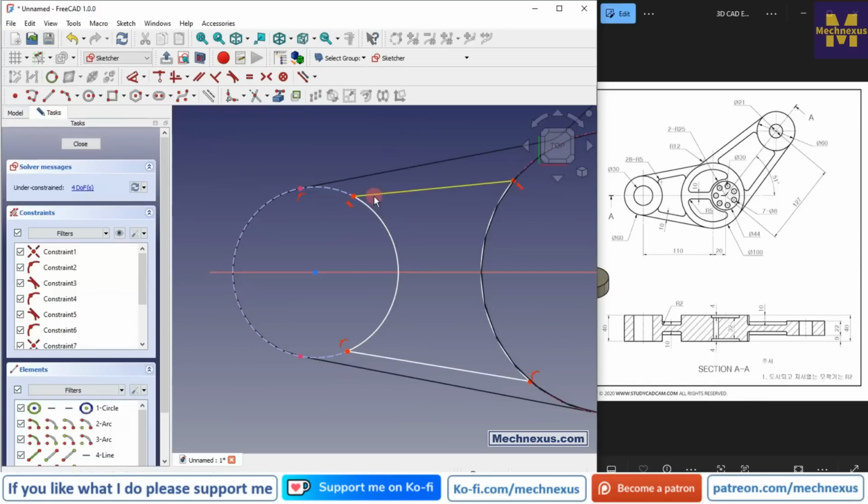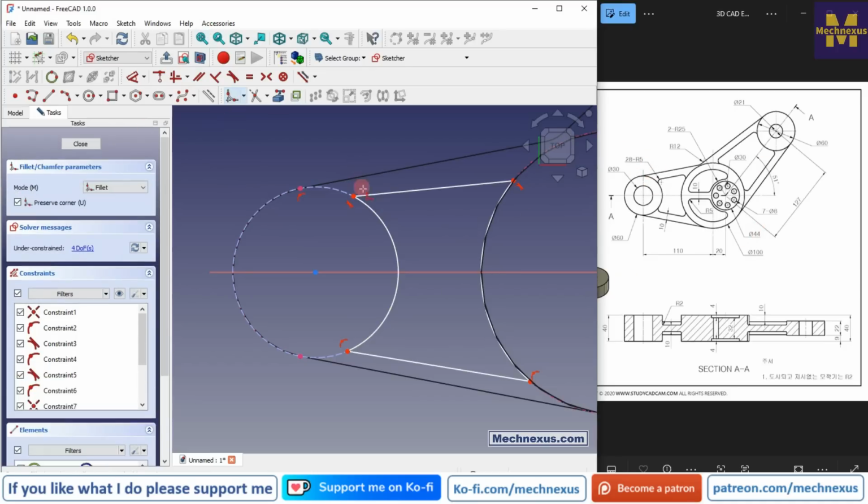So why am I making the fillet inside the sketch? Because FreeCAD fillet issues are very common, so to avoid that I am creating the fillet inside the sketch, but you can also give these fillets at the end. Now I will select a fillet tool and select this line and arc, select this line and arc, select this line and arc here and here.